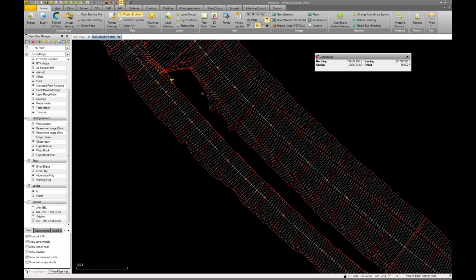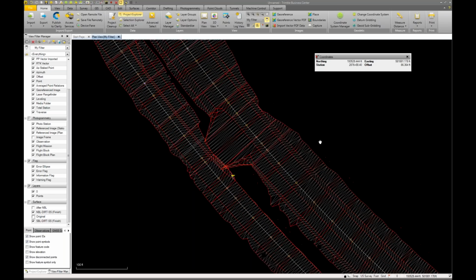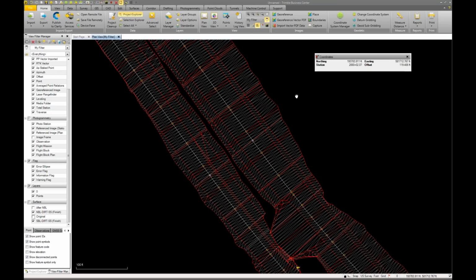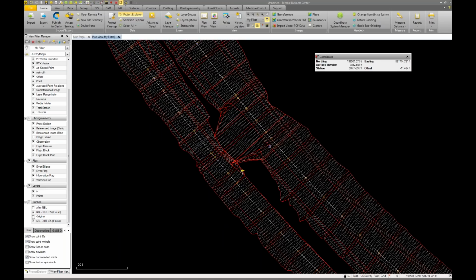some of these checks, like you mentioned before, a lot of these are just visual, looking at, do these string lines connect correctly? Does everything look right? How are my side slopes tying into my original ground? All of that. If I need to go into a particular part of the corridor and do some edits or modification, I can click near where that template's assigned, where those yellow squares are on the screen.